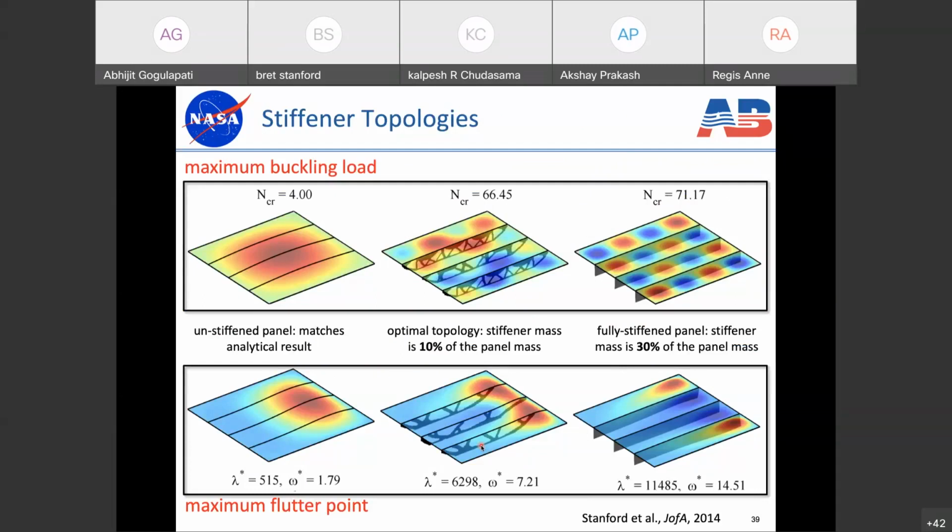No, I think they're concerned here in the States anyway. They want to make sure that every ounce of that structure, any load bearing area of that structure, is going to be satisfactorily safe. So even though it's internal to the structure, we still have to prove out a certain amount of robustness and safety factors of the internal structures as well. And this is a big challenge because, as you say, if you look at a rib today on an aircraft structure, they'll have lightening holes in it, but they won't look anything as weird as this.